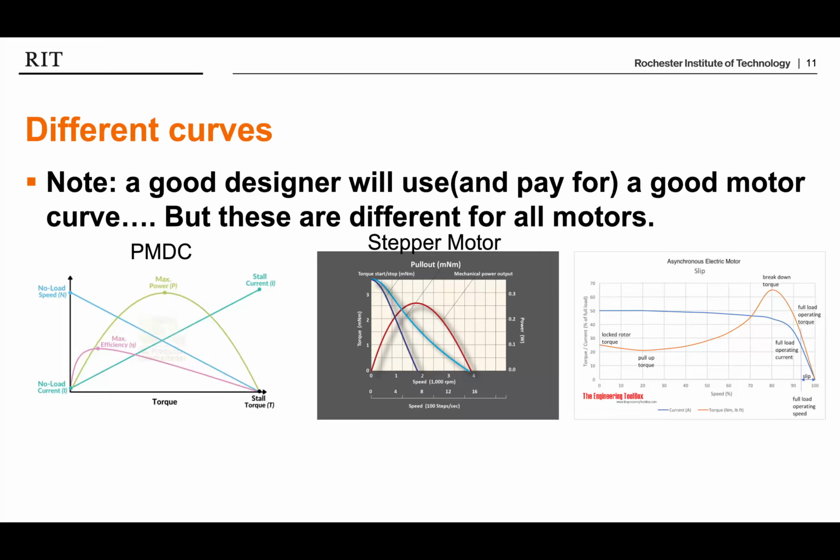And I want to say that again one more time for those taking notes. Stepper motors have the worst efficiency of any of our motor technologies. When they are not rotating, they are still consuming current, which means they are producing no power but drawing current. The benefit again, though, is they will hold against a load. So we don't really think of it as stall torque so much as holding torque.